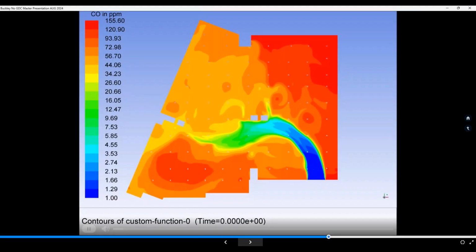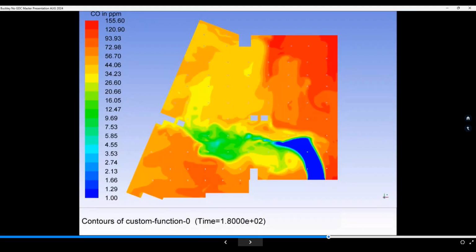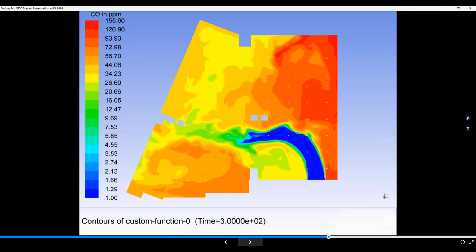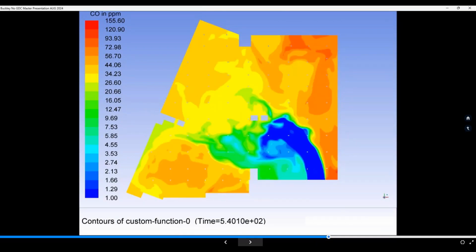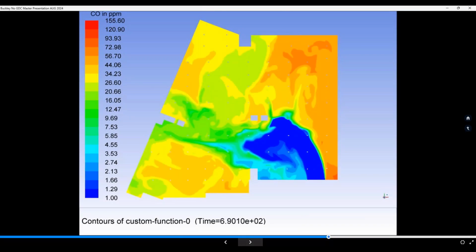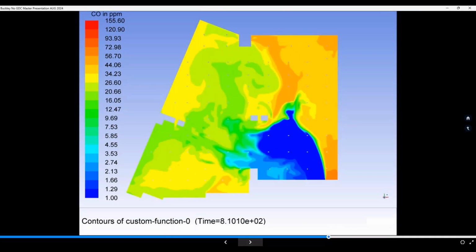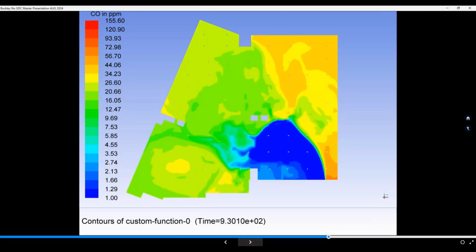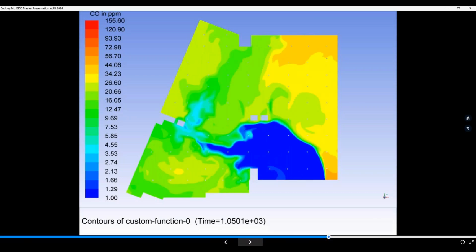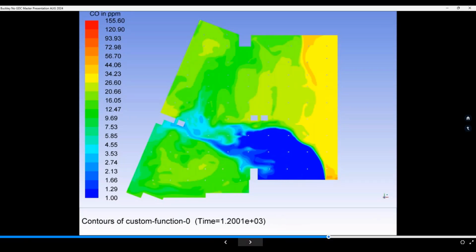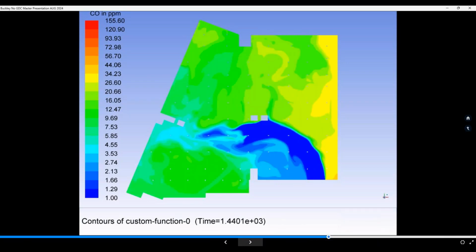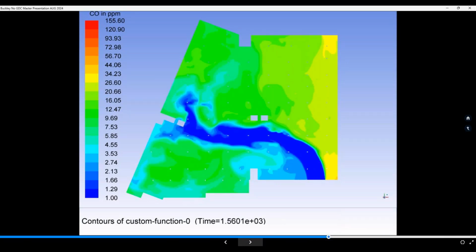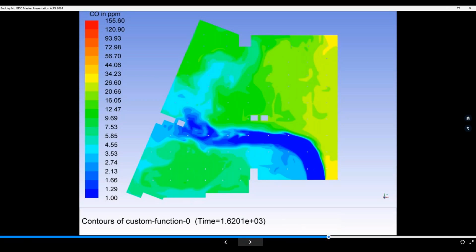And we counter that here with the jet fan system. As you can see now, we strategically placed jet fans to capture that inlet air. We're no longer relying on it to be under its own momentum due to the influence of the shaft air. We are actually influencing that air, capturing it and pushing it where we know it needs to go, for more uniform dilution throughout the entire garage space. That's a big difference.